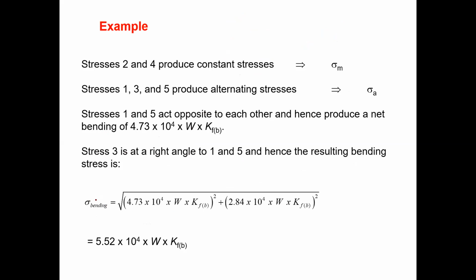So as I told you, you can get the one single stress for these two net stresses. So there is a value x, that is x squared, this is like y squared, and take the square root value. So you can end up somewhere here after simplification. This is the one single alternating stress, sigma A. Okay, this is sigma A.